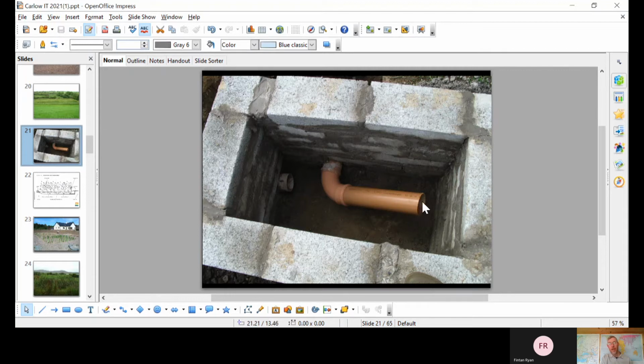If we raise that pipe fully, up into an upright position, it holds the water in the wetland. If we drop it down, it means that we can plant the system in relatively dry conditions, and then we bring it up to about 4 inches in height for operating depth, and that controls the level right across the system. That's particularly useful for domestic systems, so when you go on holiday, your system just stays moist. And then as soon as you start flushing toilets, water starts flowing out here at the far end again.